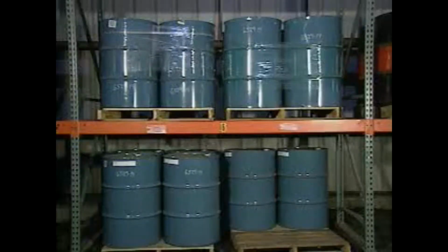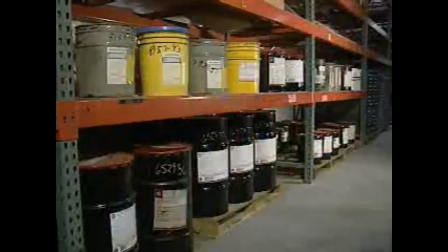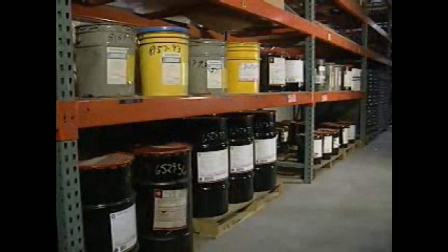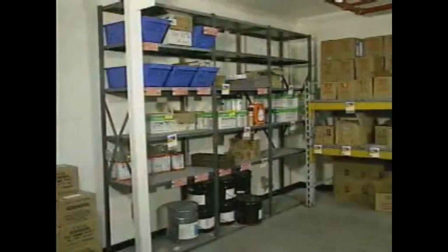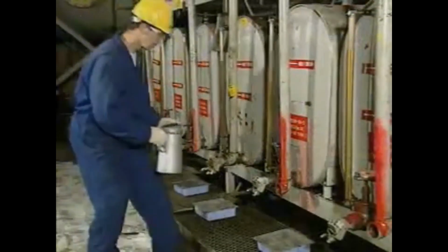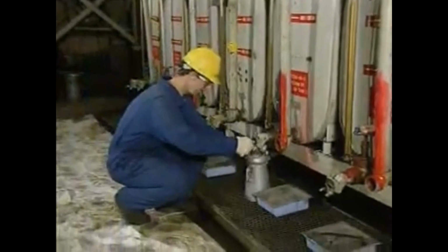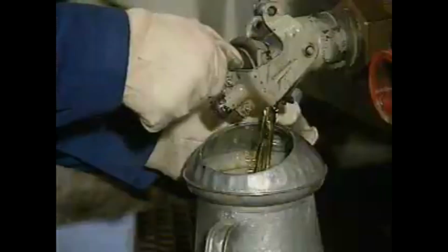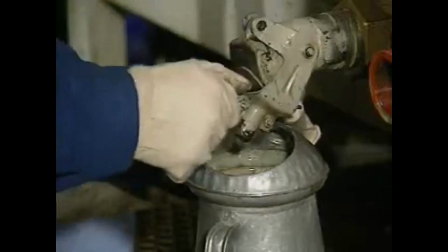Position storage racks or shelves so that all lubricants can be reached easily. Make sure that all containers are plainly marked to identify their contents, and store the containers so that their markings can be clearly seen. If possible, store opened lubricant containers and containers of contaminated lubricants separately from new unopened containers. To dispense lubricant from a drum by gravity flow, store the drum in the horizontal position on a rack and equip the drum with a spigot that has a drip-proof valve for withdrawing the lubricant.